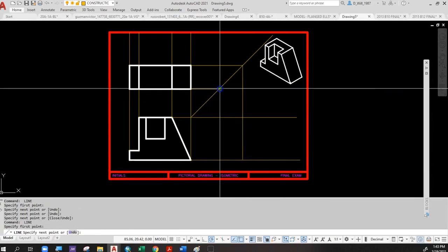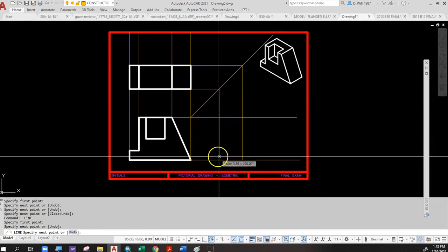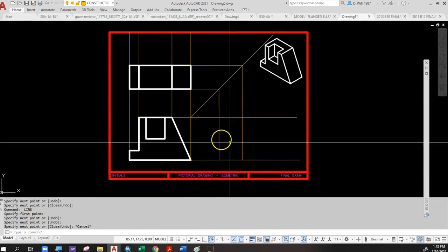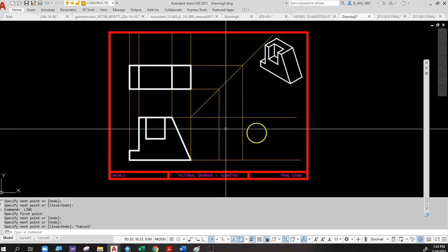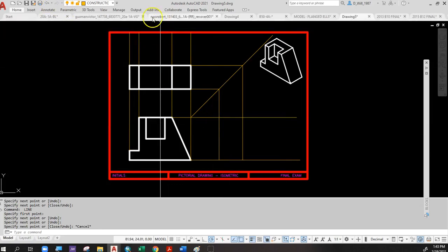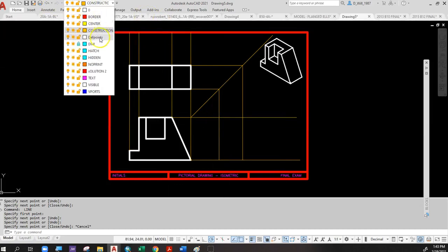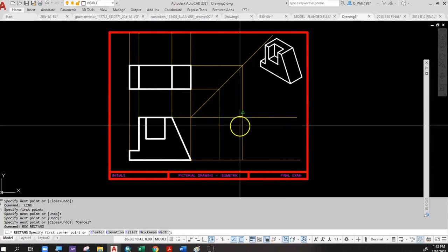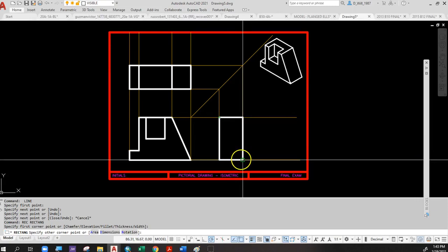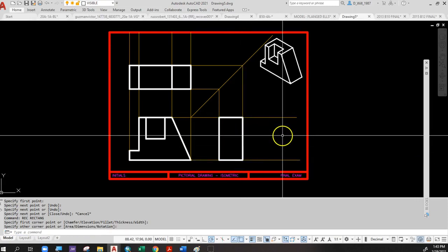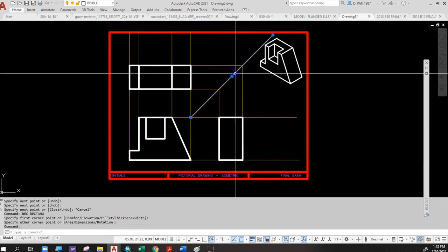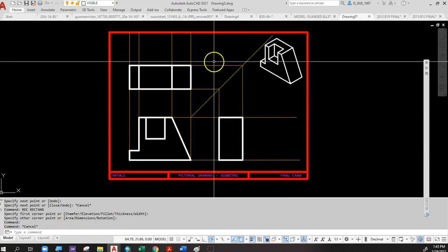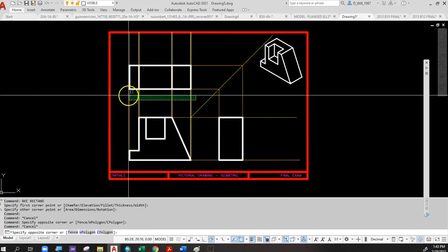So we're taking that dimension for the depth and we're wrapping it around a 90-degree corner. And that gives us the same exact size over here. So you don't have to go in and measure things from scratch. If you draw like that, where you're just measuring things and not projecting things, at some point you're going to make some horrendous mistake. And you'll have no one to blame but yourself. Projection never lies. That's my point. If you project, you'll always know what you did and why you did it.